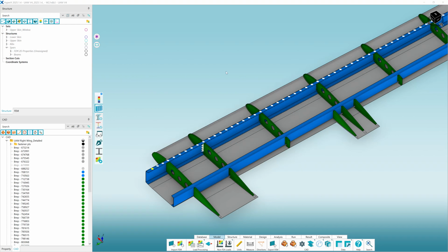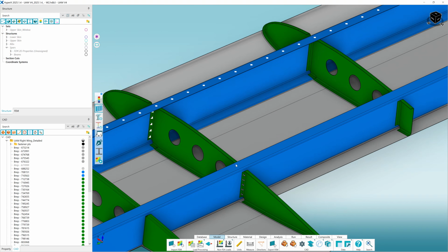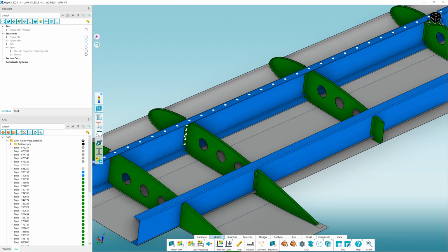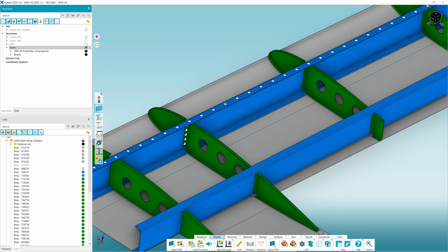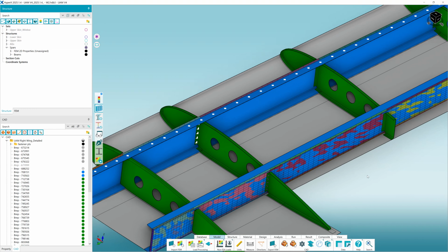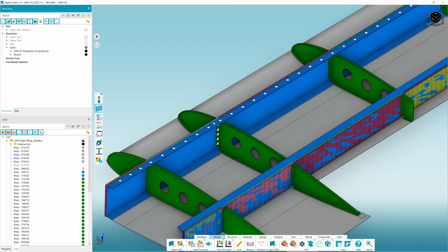All right, so I'm going to clear those fastener measurements. There's one more CAD import related story that I'll show here before moving on to the export, and that's related to the spars. So let's pretend here that maybe our spar geometry is fairly locked down. Let's say our team is moving on with procuring the tooling for the spar, so we can no longer change the width of the foot of the spar, but maybe we're still allowed to change the thicknesses of the spar.